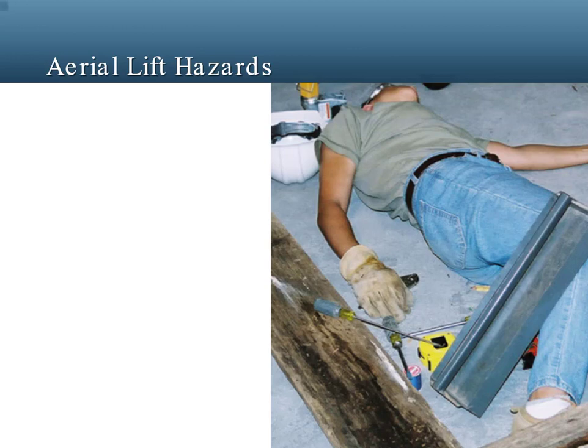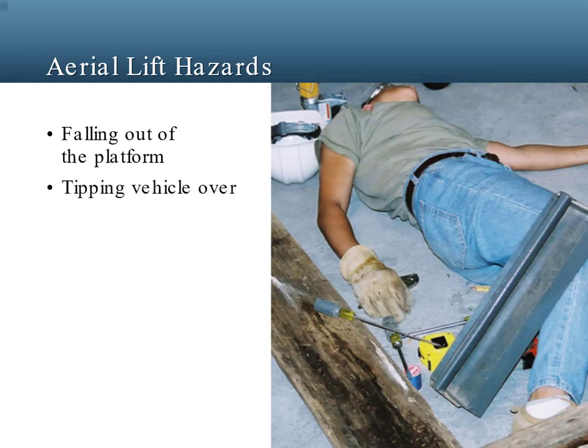One of the most common hazards of working in aerial lifts is falling out of the platform or bucket. Make sure you use personal fall arrest or travel restraint systems and that guardrails are maintained in good working order. Another common hazard is tipping over the vehicle carrying the lift. Tip-overs can occur if the lift is overloaded or if the vehicle is not properly stabilized before use. You need to know about load limits and how to maintain stability of the vehicle to prevent tip-overs.